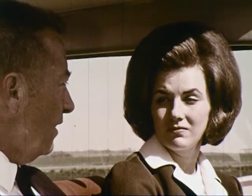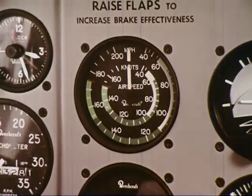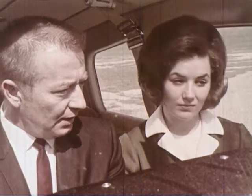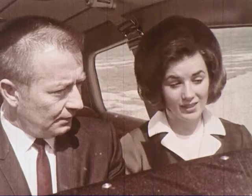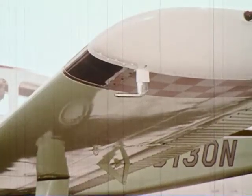Okay, now let me get this straight. We use the altimeter to determine our height above the ground, or the altitude. That's right, the altitude from the altimeter and our speed from the airspeed indicator. It shows us approximately how fast the airplane is moving through the air. This is determined by the velocity of the air entering the pitot tube. Now where is this pitot tube? It's located under the leading edge of the left wing. Okay, the airspeed from the airspeed indicator. That's right.